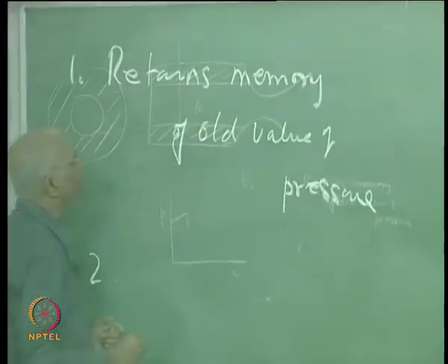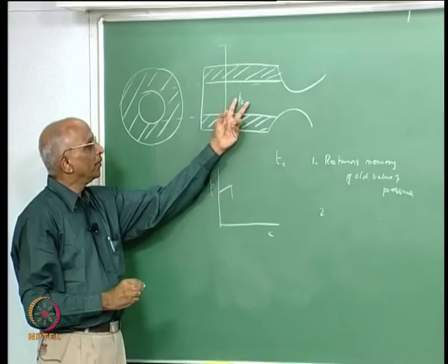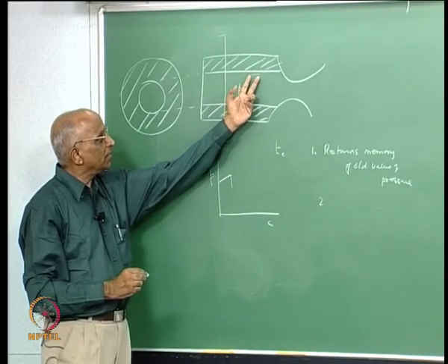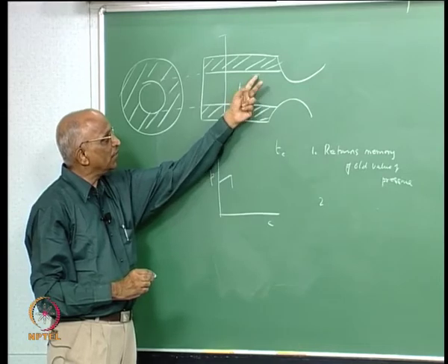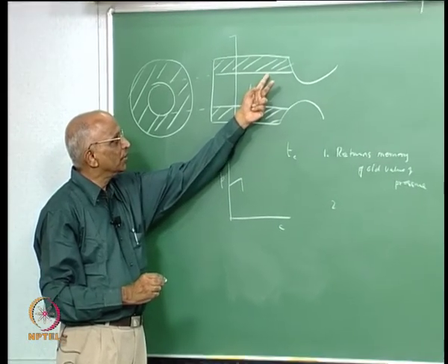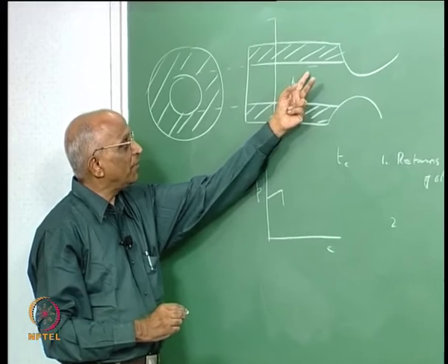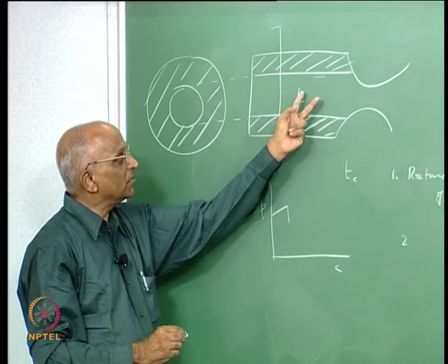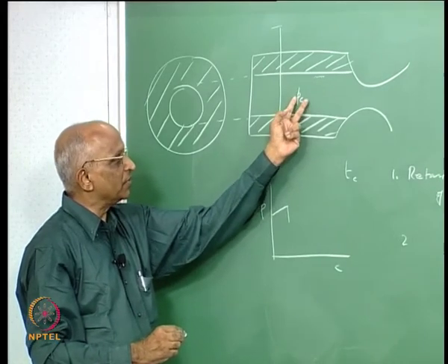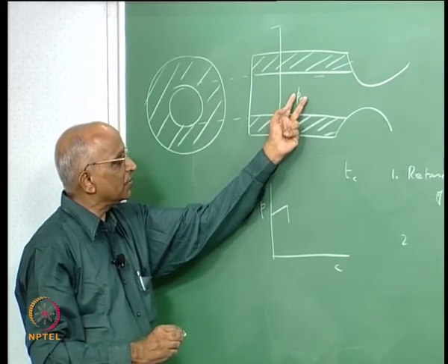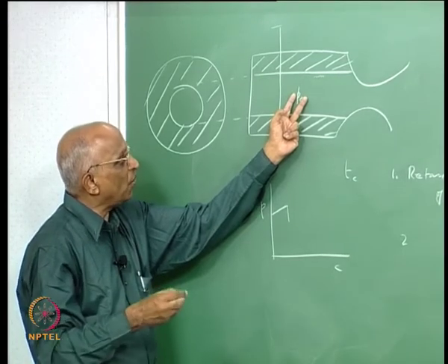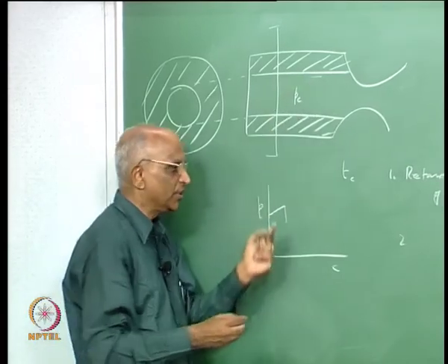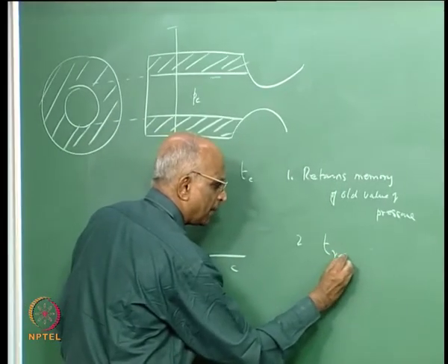Number 2, the pressure has dropped. If the pressure has dropped, what is going to happen? The flame front, that is the distance of the flame from the surface, goes a little bit further, and since the pressure governs the number of molecules, the rate of reaction decreases. If the rate of reaction decreases, well, the rate of generation of hot gases decreases, or else the velocity decreases, and if the velocity decreases, the residence time increases.